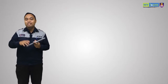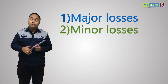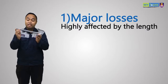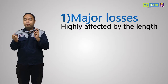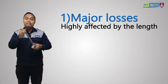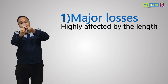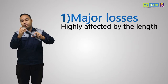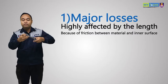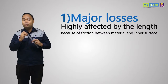The idea of losses inside the pipe: we have two different types of losses, called major losses and minor losses. Major losses are highly affected by the length of the pipe. The longer the pipe, the higher the major losses, and it is affected by the friction inside the pipe. It looks like the inside of the pipe is really smooth, but each material will have some friction inside it, whether small or big, depending on the material that we are using.